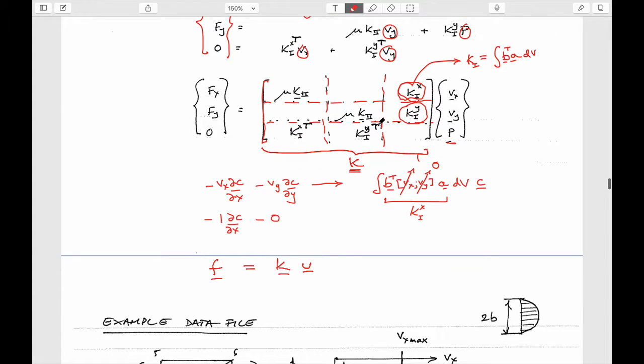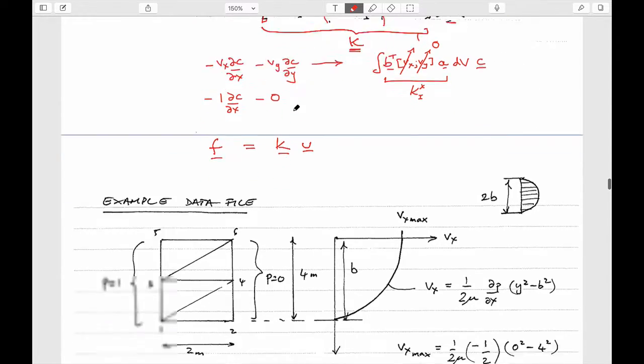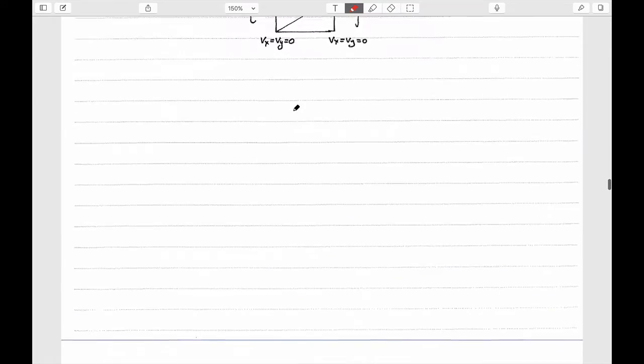This would be for a single element. These would be not displacements but velocities, and it would also include the pressure, the so-called solution vector. And these would be the body forces which we have in our system as well. And this would be the matrix which we have to make up of these submatrices. These are individual matrices, and the size of these matrices will depend on the particular shape of the element that we include. Okay? So let's figure out how we might go about doing that.